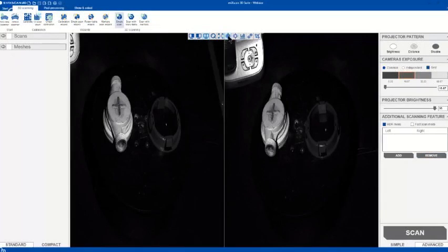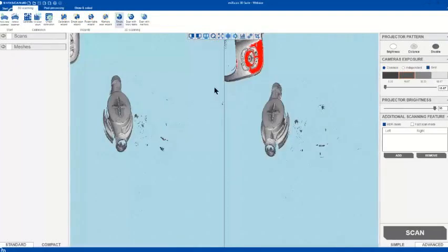We'll turn on the exposure filtering. As you see, now we've got filtering for the overexposed pixels, which appear as a red blinking area, and underexposed pixels, which are completely hidden on the live screen. So we can set the first exposure level for that standard white powdered object.